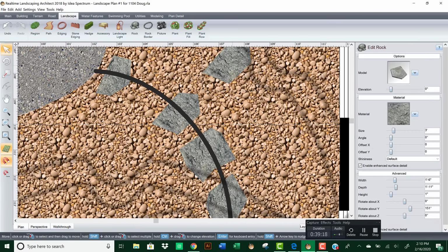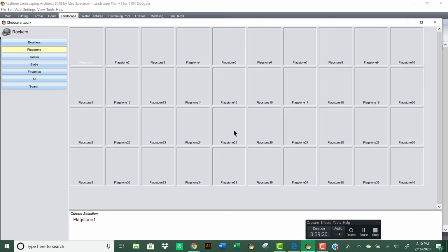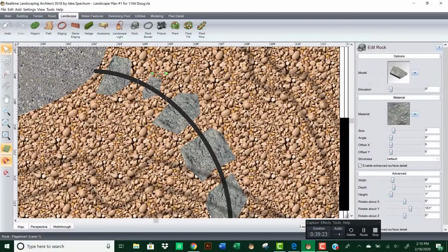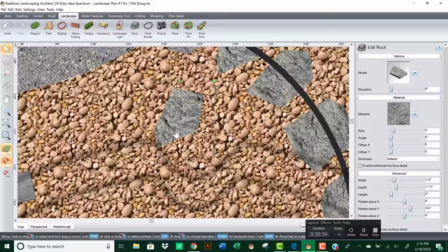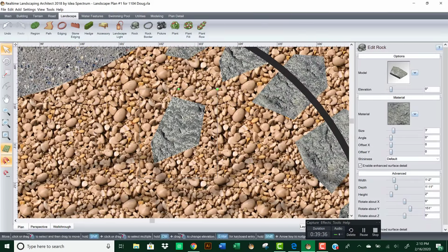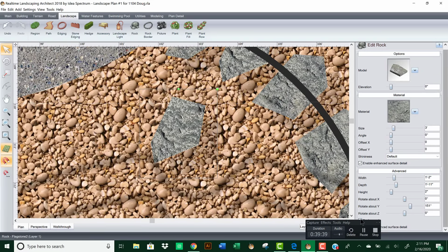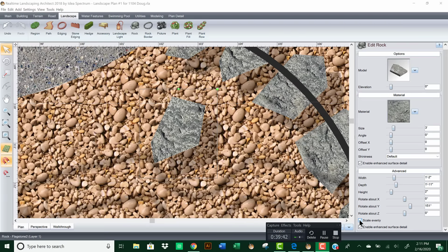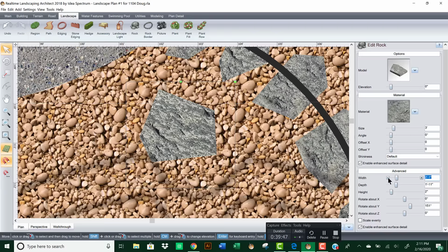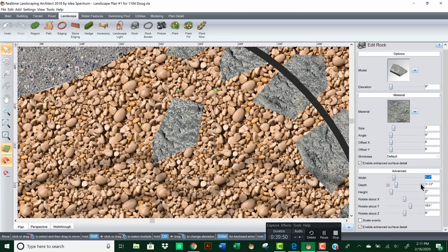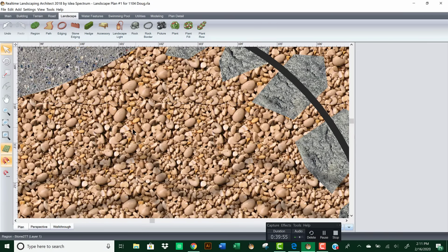Let's copy paste that one. We'll put it in there and just change the shape ever so slightly. For instance, let's say we want this piece in this shape, but we want it wider. We can scroll down here and unclick this box, scale evenly, and you can actually change just one side of this object. You can pull two edges instead of scaling the whole thing evenly. So that tends to work well for a number of different tasks.